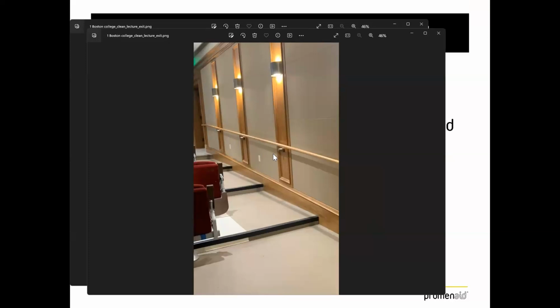Rob, before you go, we have someone asking about the maximum distance between brackets. So if you want to talk about that and how much weight they can bear. Yes, great question. So we designed them nominally to be every 32 inches, which should be every other stud in a residential setting. But we know that studs are never where they're supposed to be, and we wanted to build some latitude into the whole system. So they can actually go quite a distance.